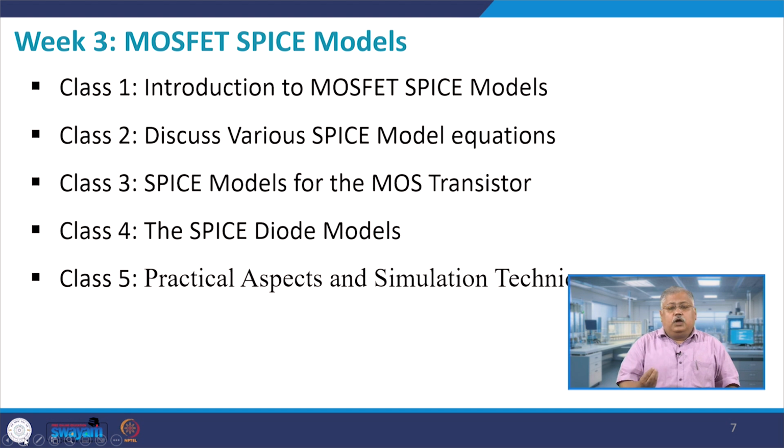So, you should be aware of how the SPICE model fits in a MOSFET, so that you can actually manipulate it in a proper fashion in order to discuss the various MOSFET models, SPICE models in MOSFET. There are various levels of SPICE. As the level goes on increasing, the accuracy becomes better and better. However, the time taken for it to converge to a set of values will also be very large.